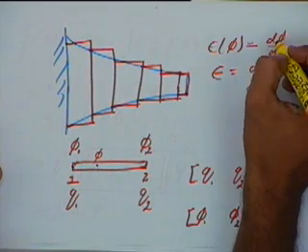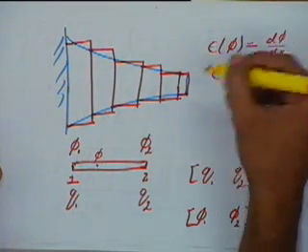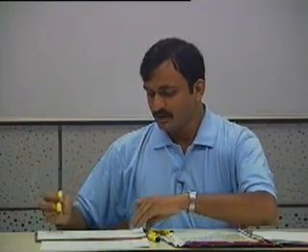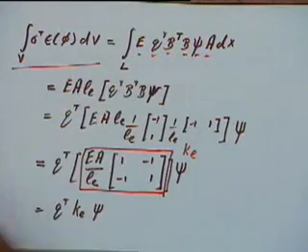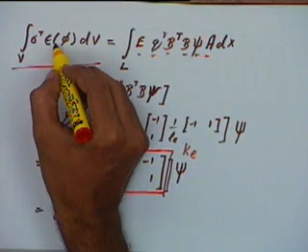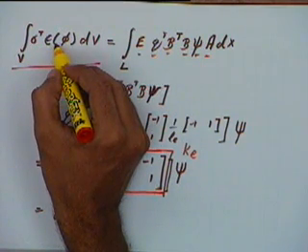So when I give it a virtual displacement, the effort involved in giving a virtual displacement will be doing some work against the internal stresses. Those internal stresses are actually the stresses caused by the loading. That internal work done is this term. That is why I have a term of the actual stresses multiplied by the strain caused due to the virtual displacement.